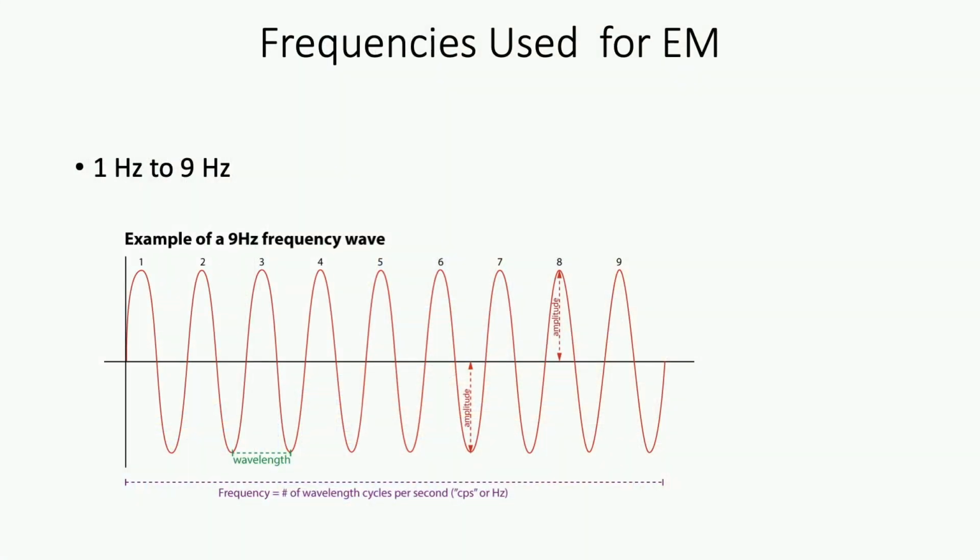Back to the EM tool. So we utilize a 1 hertz to a 9 hertz frequency that is being spit out from the dipole itself, which is pretty slow, as you guys know. Usually we use a 7.5 hertz. That seems to be our happy medium with the noise to speed that we need. And like I was saying to Graham earlier, we utilize a chirp frequency, which goes down and then comes back up, and then we utilize error correction too. But that's really slow. It's like half the speed of regular chirp.